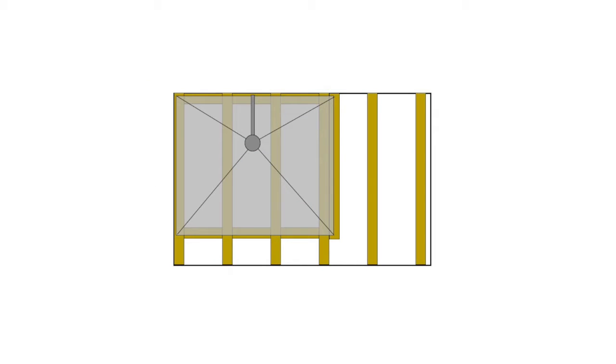Extra noggins and tray support. It is well worth producing a plan showing the joist positions in relation to your planned shower tray former. The edges of the shower tray former must be supported by joists or noggins running between the joists. There also needs to be sufficient room on the top of the joist to make a butt joint between the edge of the former and the rest of the floor. This process is not difficult but takes a bit of thinking about.